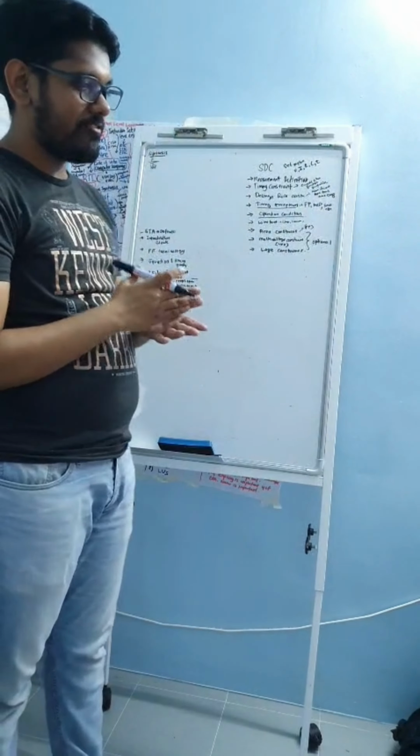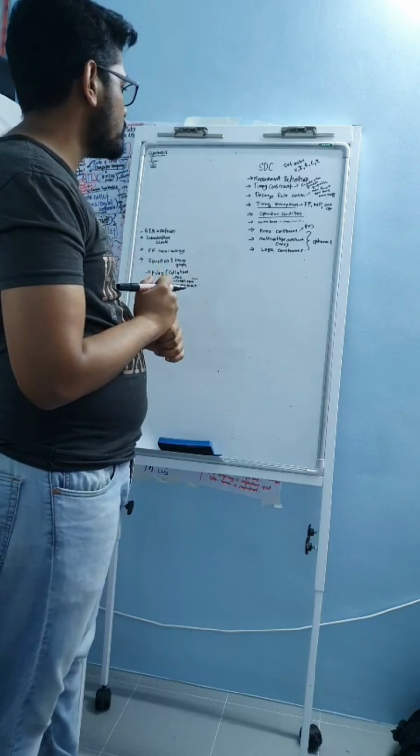Sometimes certain paths might not actually be valid, so that's the reason we set false path. Maybe certain paths can't be met within one cycle, that's why we need multi-cycle path. We need more cycles to actually meet the timing. And then set case analysis: you might have some boxes where you intentionally want to set case analysis. So there are more timing exceptions to it. Okay, I think that's pretty much all we need to know on the SDC part.